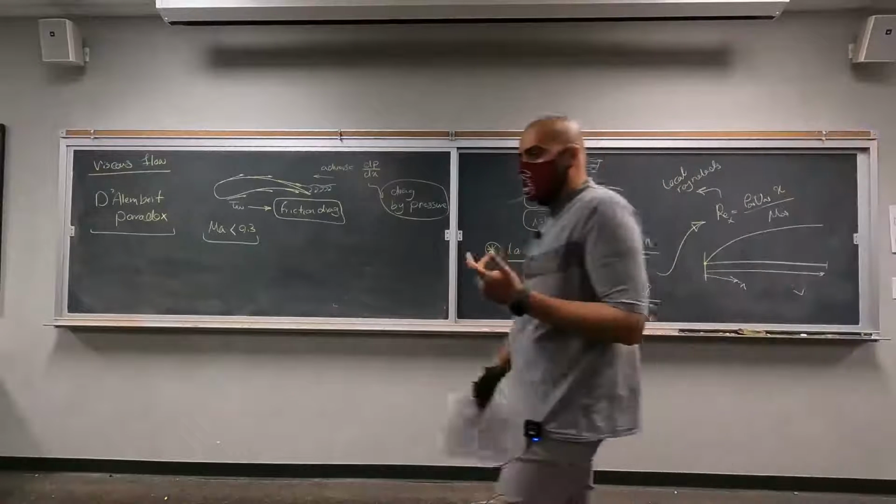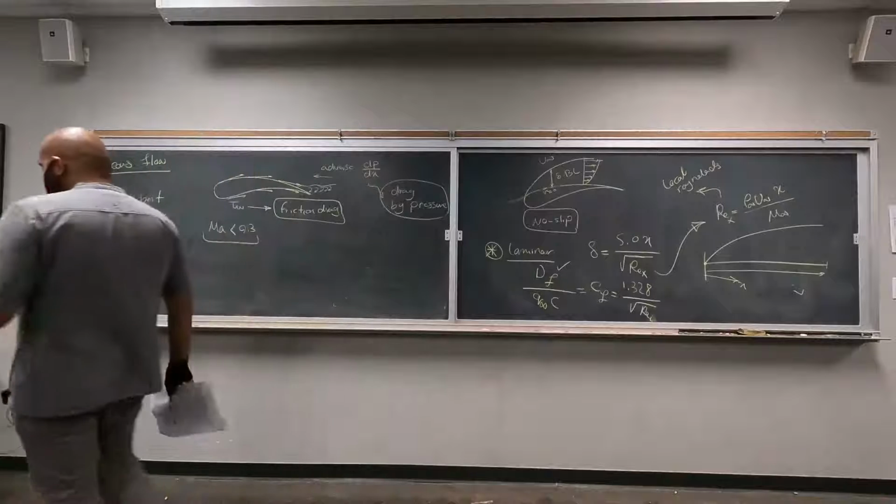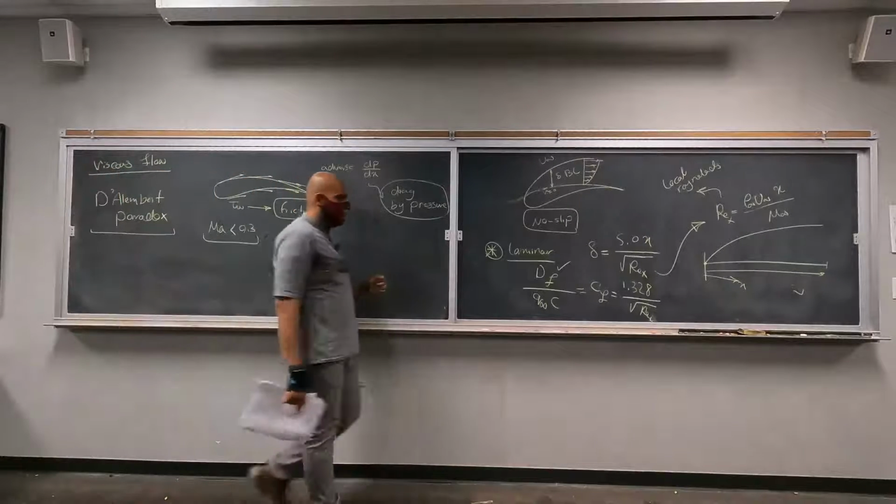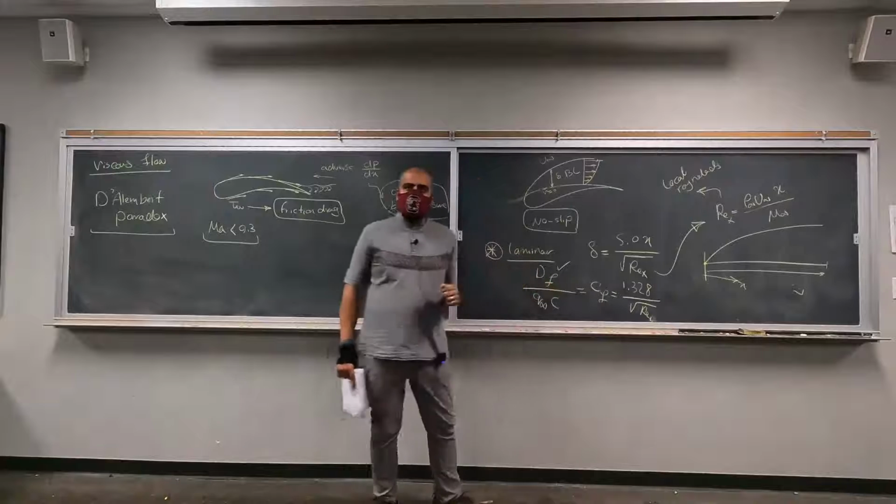So pretty simple. In a laminar region, you calculate the Reynolds number of the plate. Then you plug it into this equation. Then you find the friction drag. Yes.